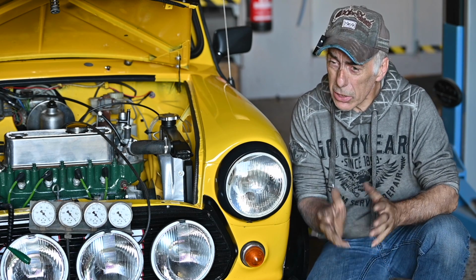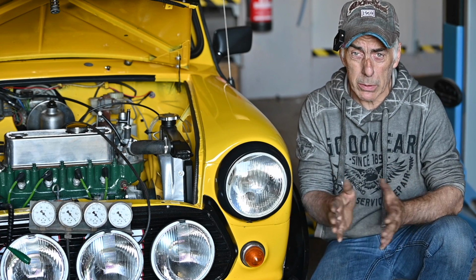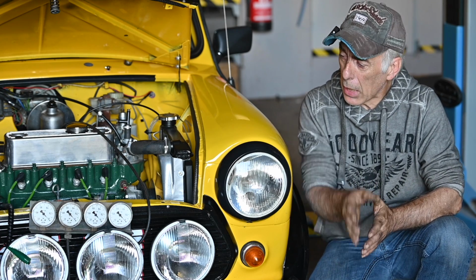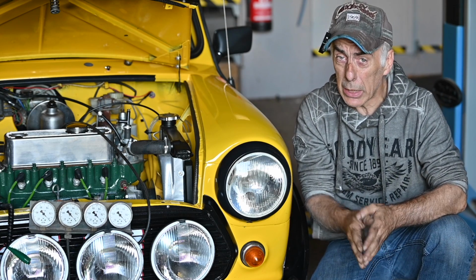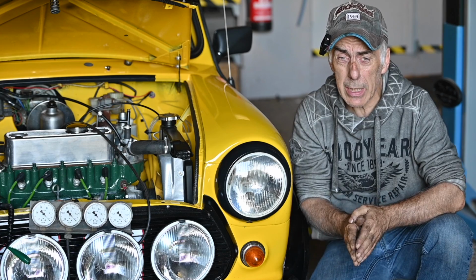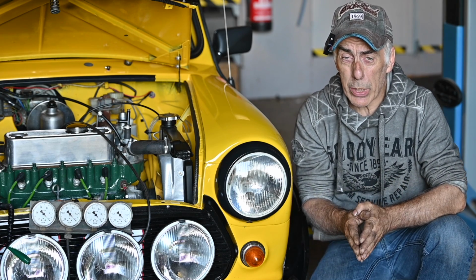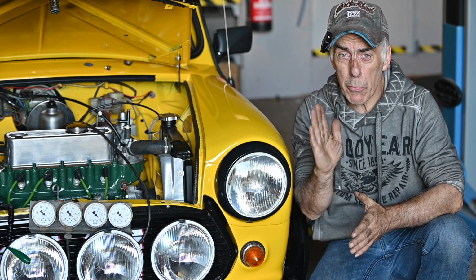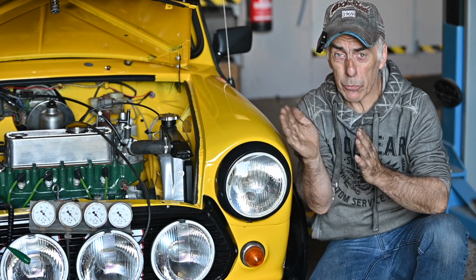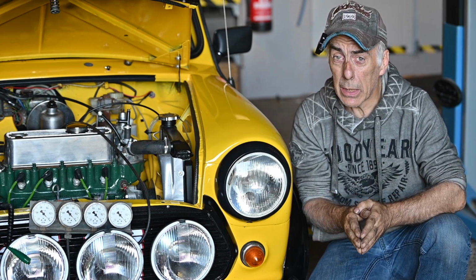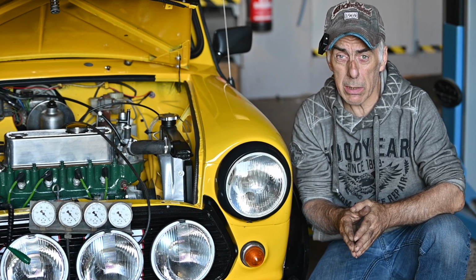Now the other method is using what we call vacuum. It's a vacuum advance mechanism, and we know that the intake manifold is creating vacuum. And I hooked up a vacuum meter, and I'm just going to measure the idle vacuum in a second to show you that it does create vacuum, and of course you all know this. And the more RPMs you make, the more vacuum it creates. If you were now to apply this vacuum to a membrane which is fitted to the distributor, then the membrane can pull out the rod and advance the notch in the distributor. And that's the other method that we apply in cars.